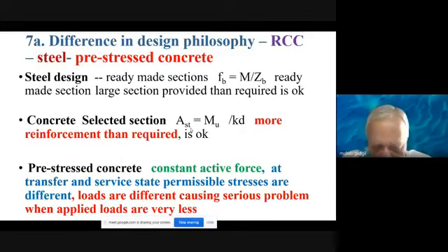But in prestressed concrete, I cannot say that if I want to apply two cables, for example, and it is able to satisfy all my requirements, then to be on the safer side, instead of two, you use four cables, and instead of applying 30 ton force, why not apply 40 ton to be on the safer side? Oh, that's not correct. In prestressed concrete, you cannot go on the safer side in this way. This is going to make the structure unsafe.